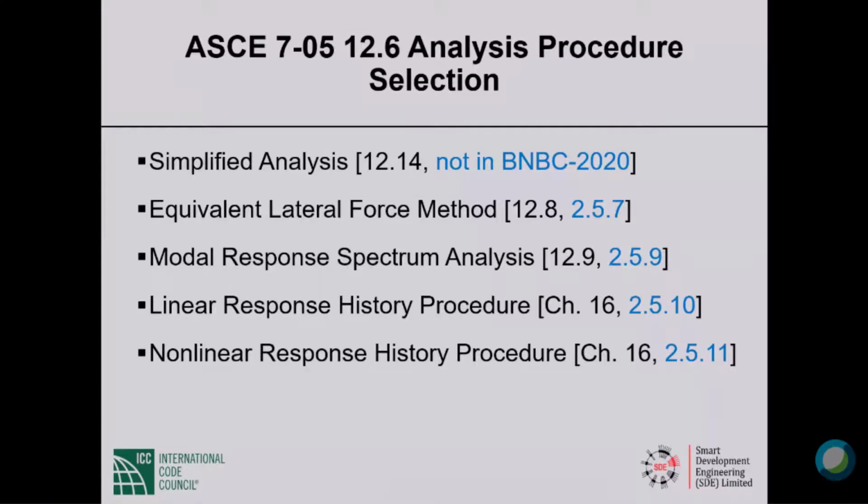Nonlinear response history analysis, chapter 16 and 2.5.11. Equivalent lateral force is a static method. The other three are dynamic analysis methods. Equivalent lateral force procedure is allowed to be used under restrictions. The dynamic analysis methods can be used anytime.